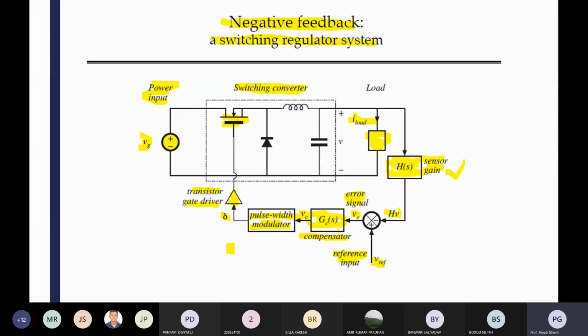If you provide that light, due to the LED light emission, that portion will be triggered. One LED lamp is there, one transistor is there. The base of the transistor is enabled by the light of the LED. So that is optical isolation, and it will feed the switching converter.